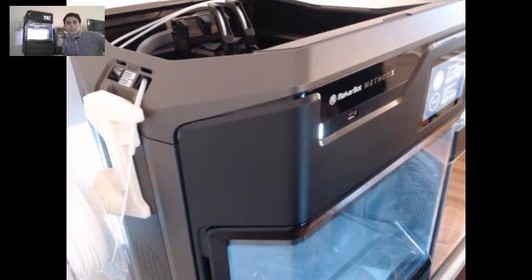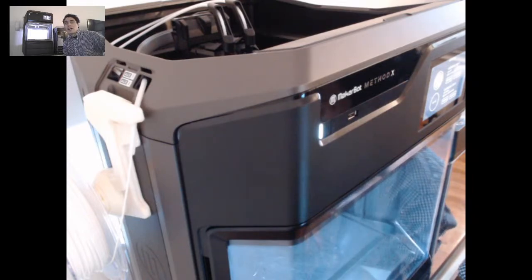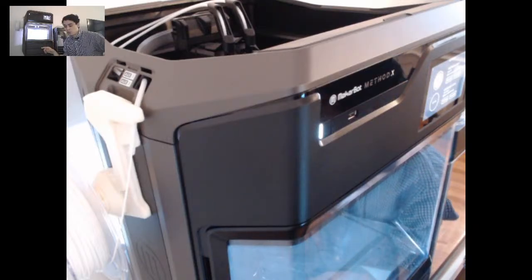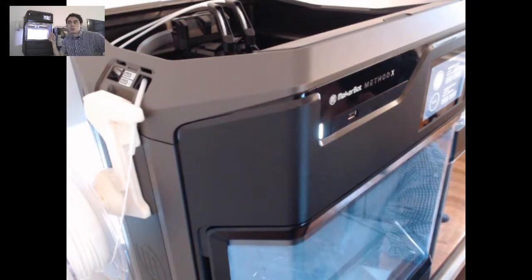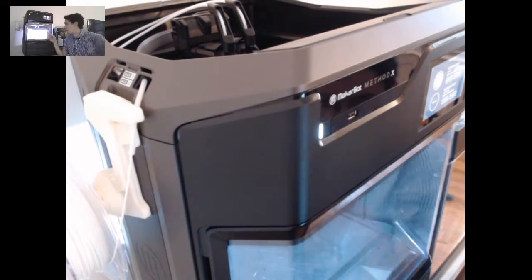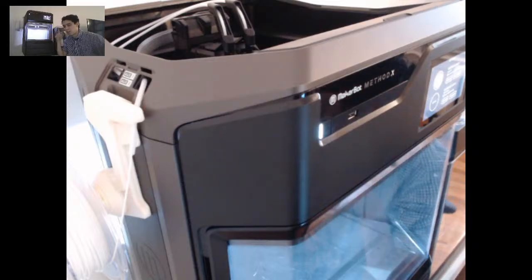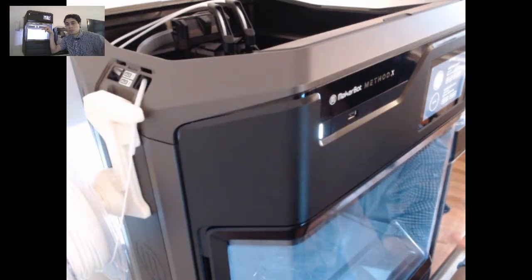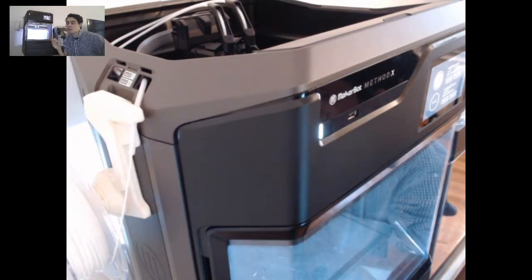Okay, so this is related, and how to unclog it. Depending on how your material is flowing, right? When you're running through the purge sequence, you'll want to see the material flowing nice and smooth and clean. And you'll want to see a single bit of material. As you saw right now, when I was purging the material, it started collecting a little bit on the tip of my nozzle. If you see that happening a lot, that might be a sign that your nozzle is starting to clog a little bit.